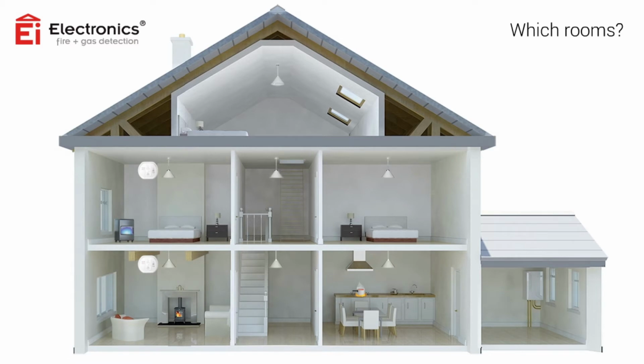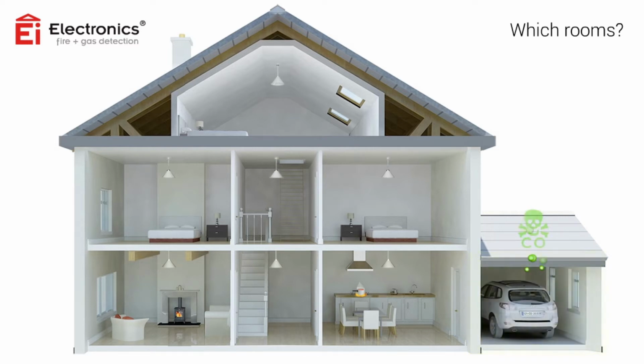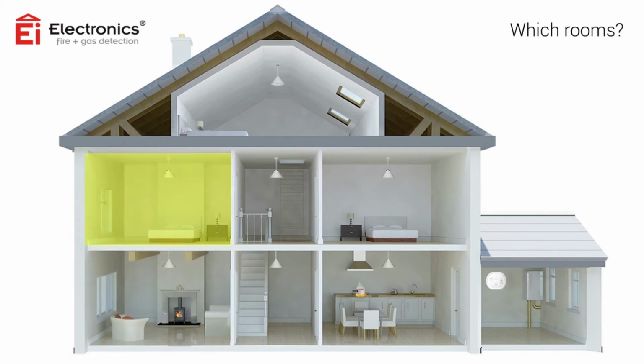If the dwelling contains only one fuel-burning appliance located in a remote room, for example, a utility room or garage, then consideration should be given as to whether or not adequate warning is given for occupants in other rooms, such as living rooms and bedrooms. If it is deemed that the alarm sound levels are inadequate, then move the alarm outside the door of the room with the appliance. If the sound levels are still inadequate, consider moving the alarm closer to the occupied area.